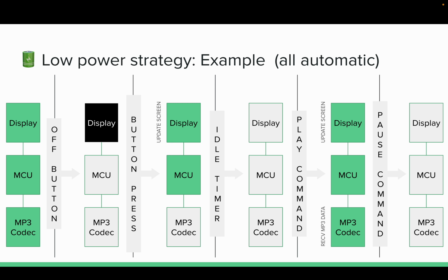That's kind of the idea, is that all this stuff should just flow naturally. If you wanted to put your system into a low power state, you would either do that at the tail end of your super loop, or you would put that at the tail end or inside your idle task for your operating system. So anytime it drops in there, you could either always try to go into idle immediately, and that depends on your architecture if it can support that, or you can wait a certain amount of time before you decide to put everything to low power, whatever your application needs.